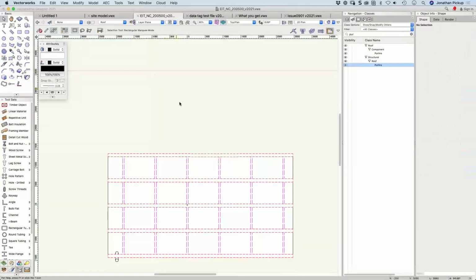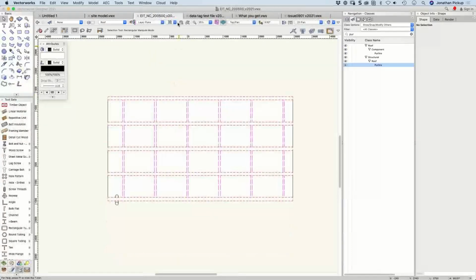So let's go to create a section through my building. Create section viewport through here, looking that way. And we're going to create a new sheet layer for this. I'm not going to worry about it, I'll give it a number, 100. Section. Okay, so there's my section.